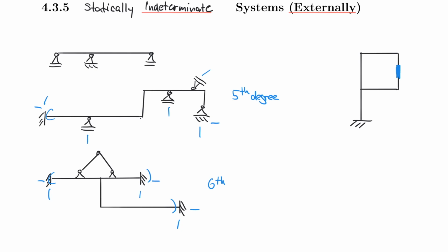I have a problem that engineers have to address, and that is that now this system here is connected rigidly, which transmits the forces from one part of the structure to another one. And you can see this is kind of like a closed frame. So think of heat being added to the system. What happens if you add heat to it? Every part of the structure wants to expand.